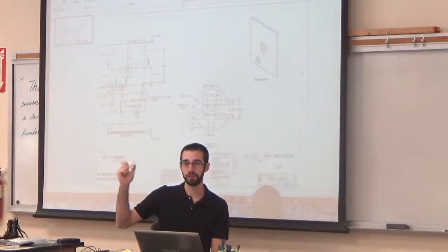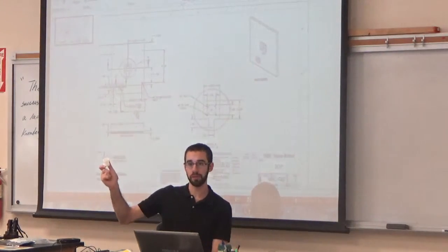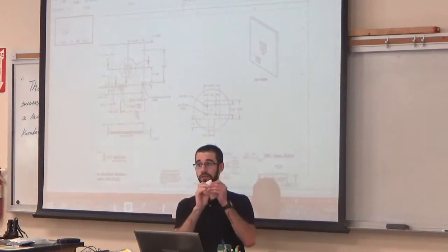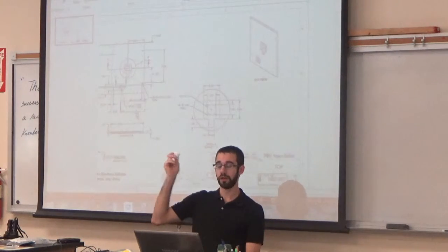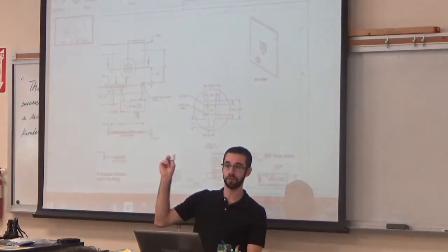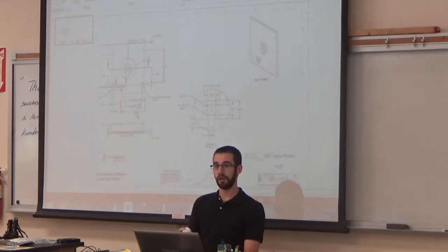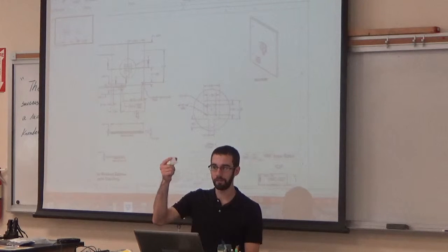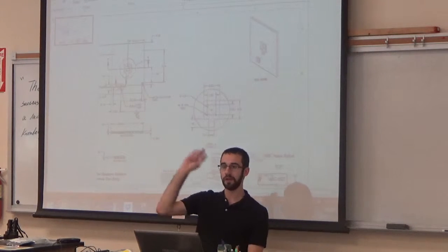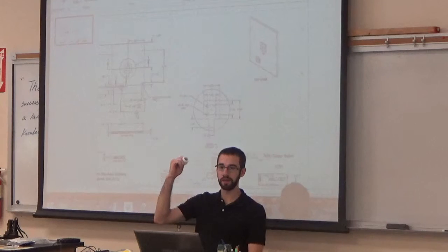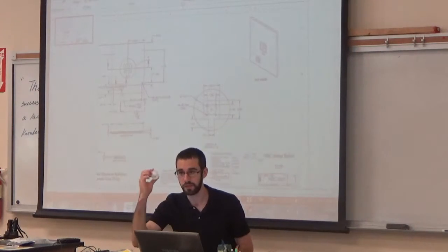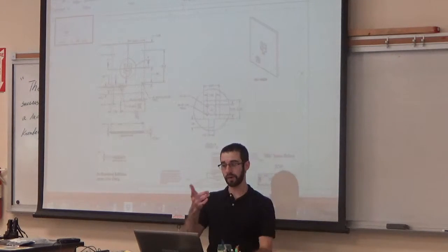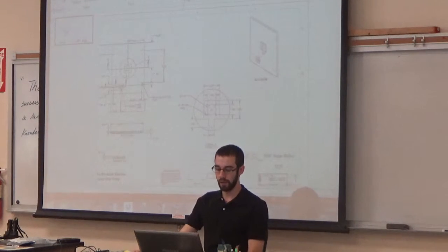And the only way we could tell our vendors that they had a problem was looking back at the drawing. This isn't the drawing of it, but the drawing would show the dimensions and the tolerances of that circle, and we could say, hey, this is the wrong diameter because it's not within our tolerances. It's a fairly simple part, but it's injection molded. We talked with our suppliers, and they said, yeah, we messed up. They sent us new batches of these that worked. We put new O-rings on them and sent out the faucets. That's one of the reasons why it's important to have these drawings.